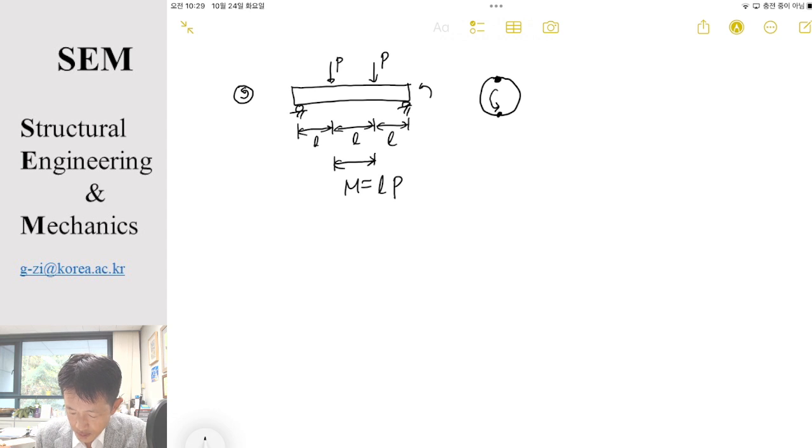That's why the same point experiences the maximum stress and the minimum stress: the bending moment times the diameter divided by 2, over the second moment of inertia, because this is a circular specimen. And that is the stress change during the rotation of the specimen.